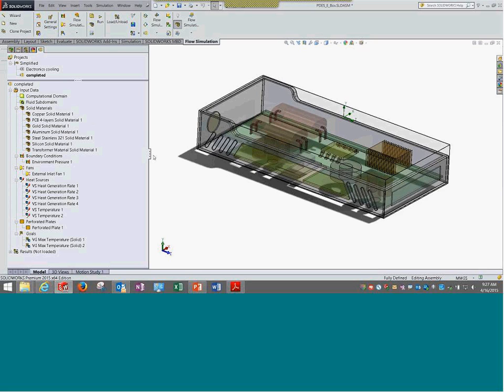Even this can be seen as a process in a company wherein there is a configuration for a detailed design, and thereon there is one more configuration which is created for simulation. For any one geometry, a company or a group can follow this process wherein they have two configurations. One is more for designing and details. The second is more for simulation.